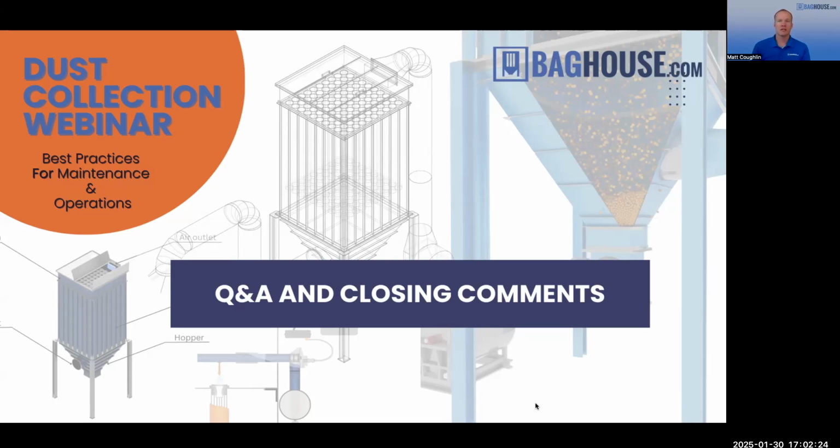And then generally there's a few little tools that you can use to help get things through the hopper, like vibrators. Worst case, you could weld some strike plates on there. So if you're going to be banging on it with a rubber mallet, at least you have a welded thick gauge piece that you're not going to be denting in the hopper. But that's the most common thing we see.